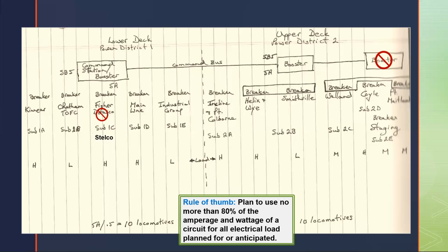If you've got a circuit that's rated at 15 amps, you don't put 15 amps worth of draw on it in your house. In fact, you're looking at about 12 amps would be the maximum they would want to see you telling them you're going to have connected, either lighting or whatever it might be, toasters, you name it. Same thing then, it seemed, needed to apply to the layout.